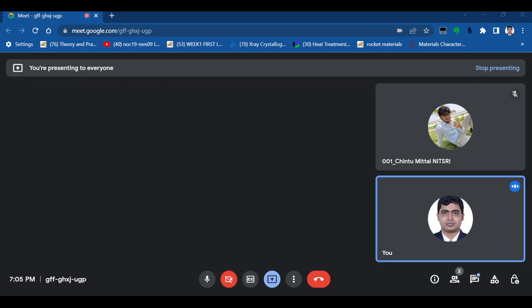So what will happen? Option A is same weight fraction of the liquid, but liquid compositions are different. Because here we know that from lever rule, what will be the composition at this point, what will be the composition of liquid and what will be the composition of solid. This red one, everything is red here. This is the liquidus line, and this one is the solidus line. So what will be the composition of liquid and what will be the composition of solid for this composition?